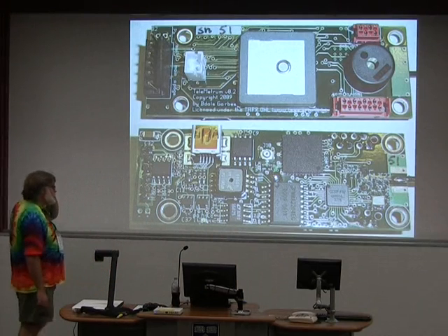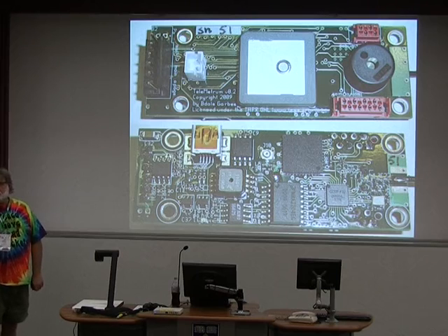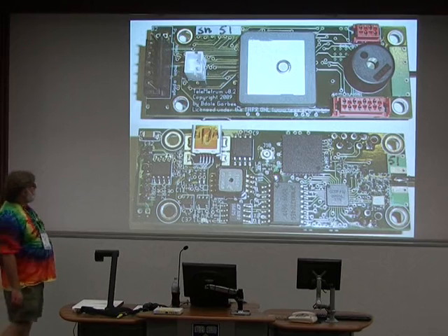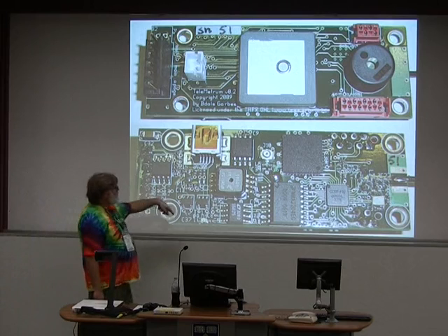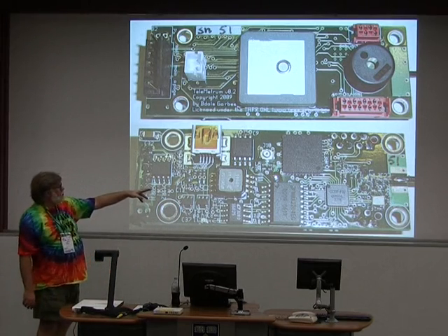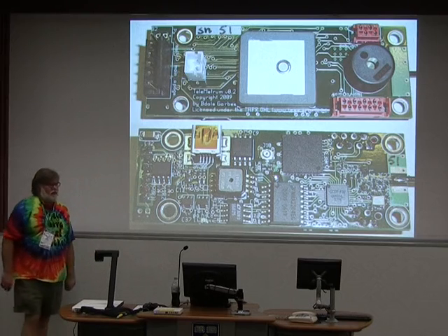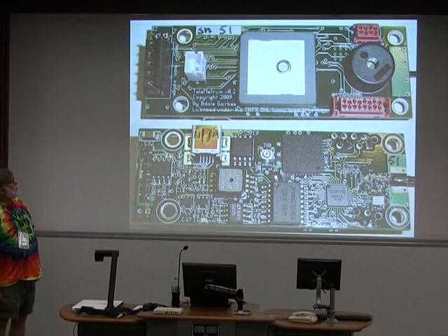The big change actually is you noticed on the previous one I didn't bother showing you the back side of the board. That's because there was nothing there. But what I realized here was that with all the extra parts I needed to stick in to put the GPS in, putting all of the surface mount parts on one side of the board and putting the through-hole parts in from the other side of the board, which I think I actually have to give Keith credit for thinking that idea up, was the answer.